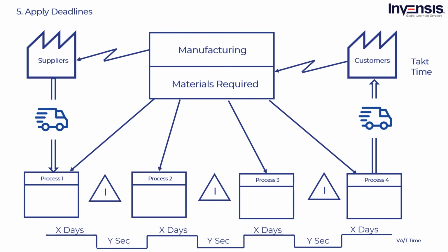Now it's time to create a timeline. Mention this at the bottom of the value stream map. The timeline has two levels. On the bottom, write down the times for value-added processes, taken from the data boxes above. And on top, write down the times for non-value-added processes. Now, calculate the time accurately and monitor efficiency.